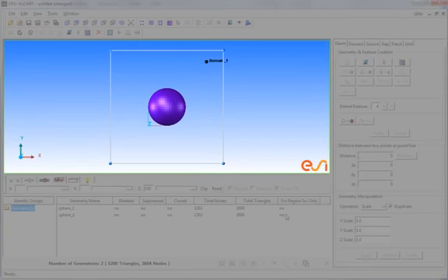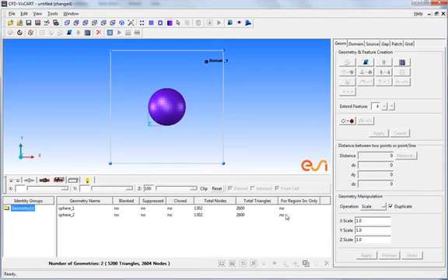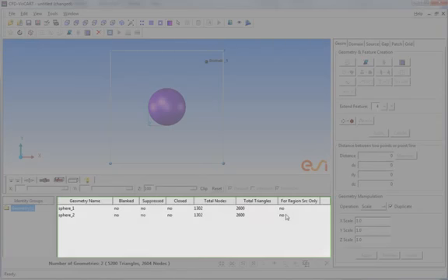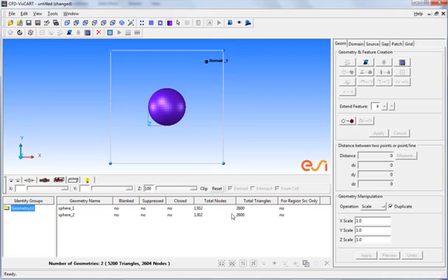This geometry includes two concentric spheres. The Graphics Viewer also shows a bounding box around the geometry and a domain marker. We will elaborate more about these entities in a few minutes. The two surfaces or patches included in the geometry are listed in the Explorer, below the Graphics Viewer. Selecting a component in the Explorer highlights it in the Graphics Viewer.